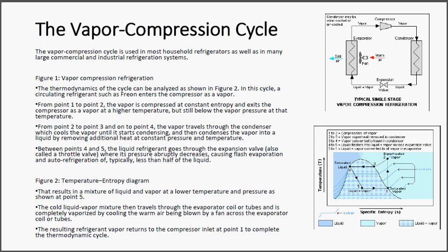The compressor in turn compresses the vapor, and again it moves it into the condenser. So you've got this circuit going on, and on one side it's very cold, the other side is pretty warm. So when you've got a refrigerator, always bear this in mind, you need a lot of ventilation behind the refrigerator. The temptation is always there to put some stuff on top of your refrigerator and to block off the airflow from behind the refrigerator. You need to have quite a bit of a gap behind your refrigerator and allow air to flow freely so that the condenser can work at its best.